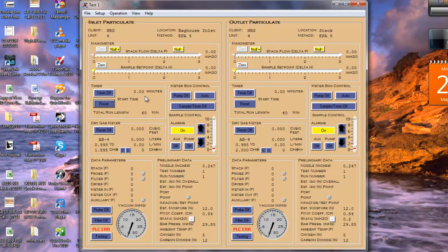So if we were going to turn on our sample pump, we would turn that pump on, and one of the things to be sure of is that the pumps are sometimes cold and they don't start up, and we usually need to confirm that the pump is on. One way to do that without anybody looking at it is to turn it on and turn this sample valve open, and if the sample pump were on, it would immediately peg this up at pass 3 and start drawing a sample, and then you would know that the pump is on.